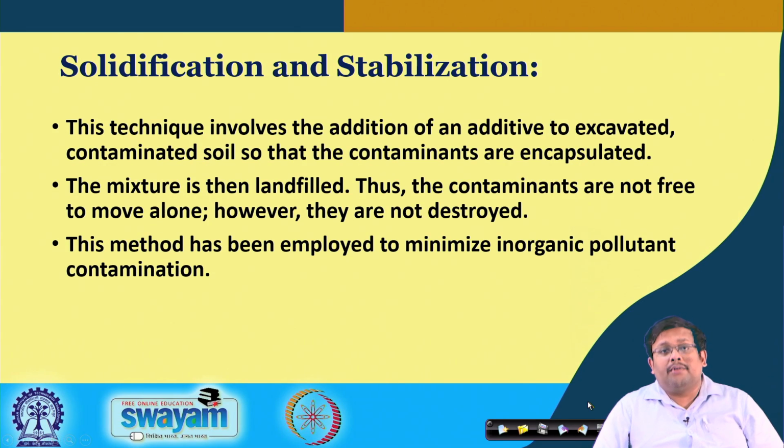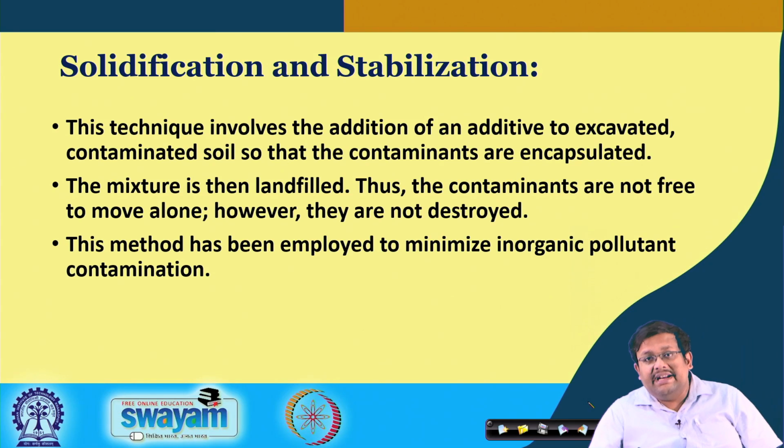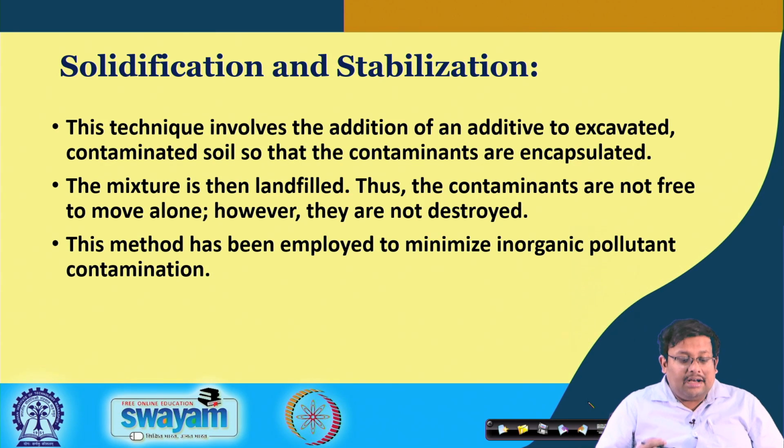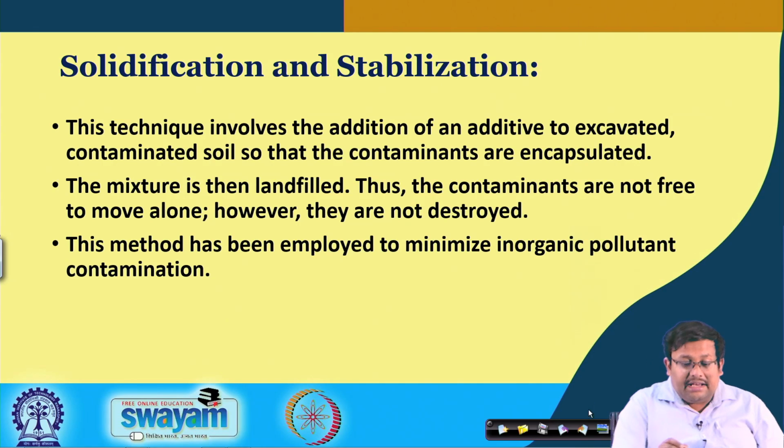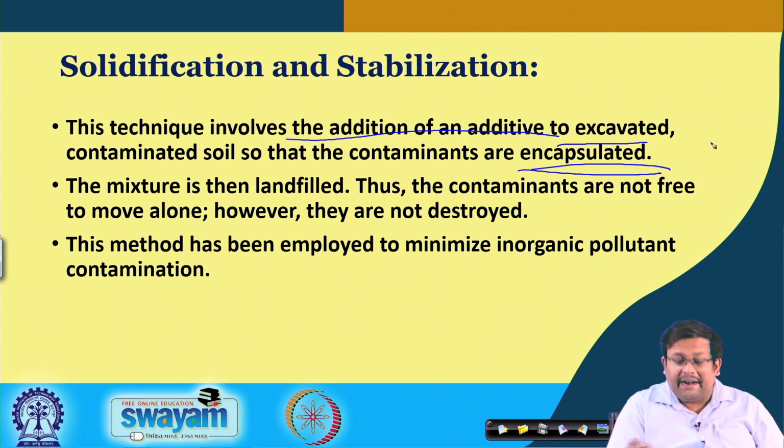and another process of ex situ soil treatment is solidification and stabilization. This technique involves the addition of an additive to the excavated contaminated soil, so that the contaminants are encapsulated, they are bound together.